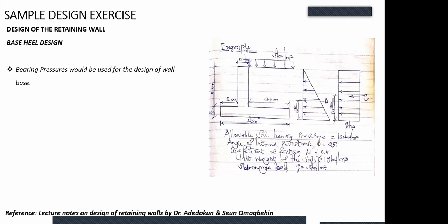So we've gotten the base pressure, the minimum and the maximum base pressure. That means we got the minimum here and the maximum here. And don't forget that our yield is starting from here up to 3.1. So it is crucial for us to get the pressure acting at point 3.1 here. Since we have what? 2 already. We have minimum and maximum. We can use similar triangles or interpolation to get what? The one at the middle.